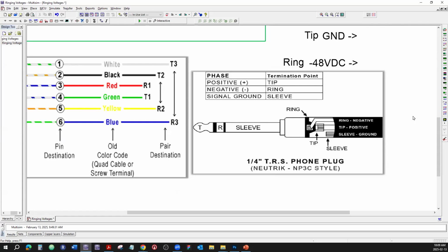Why do we need 2 tones? Well, if it was just a single tone representing a number, you pick up the phone, there could be a TV going in the background or a radio or people talking, and any kind of sound in the background could be mistaken for a number because the circuitry is listening.